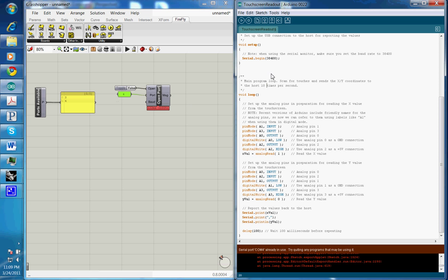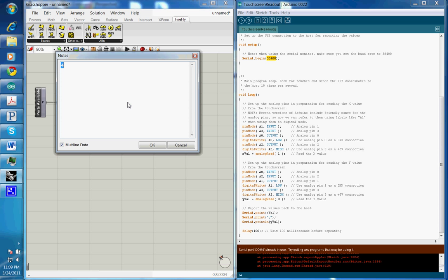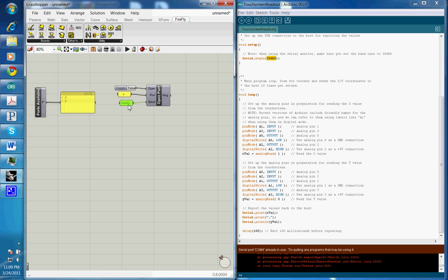And if you remember, we had the baud this time set to 38,400. So let's go ahead and give it that value. Okay, so for the port closed, because the toggle is set to false, but we know the port is on 4, and it's running the correct baud.